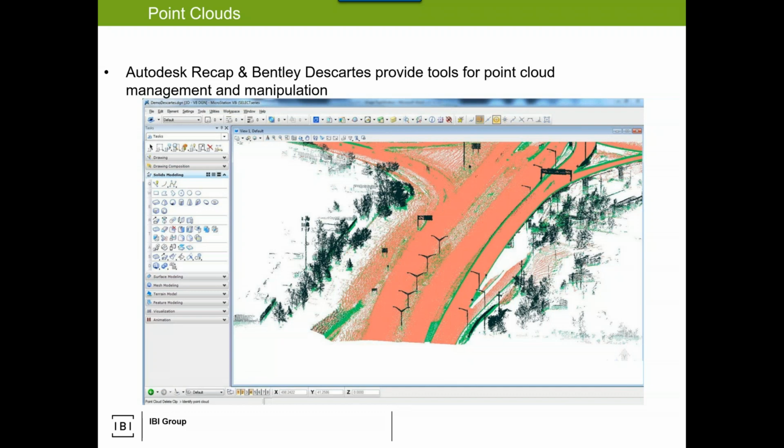If you're doing a full scan to BIM versus just a scan for reference, then there are different mechanisms to achieve that. When I teach this, I also like making mention of CADWorx. So Intergraph's CADWorx will take a rationalized point cloud and pull it into their piping modeling tool. It's kind of like a point cloud interpreter.